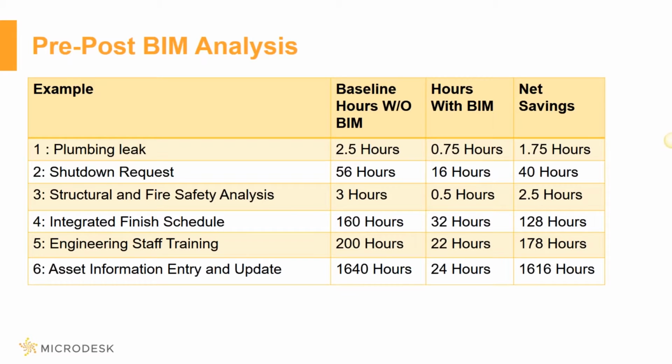Typically the integrated finish schedules are not known within operations unless you make a concerted effort to go out and record the information that's needed. But many times what they'll do is they'll just take a sample off the wall, go down to the paint store, get the color matched, get some paint, verify that it matches what the finish is supposed to look like, and then get the contractor in to do the painting.